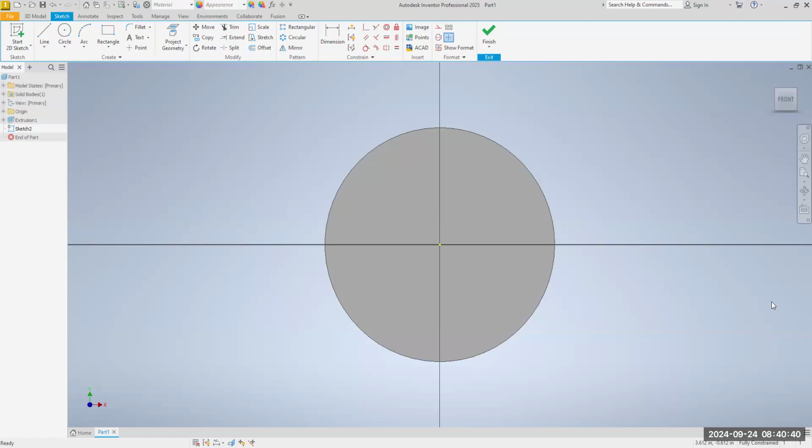Now, can somebody look at the drawing and tell me what the bolt hole circle dimension is? What is the diameter of the bolt hole circle? It's the dashed line. It's the center line. What is the diameter? Talk louder. It's 1.875 is what it should be. Okay? We're going to place 4 holes on the bolt hole circle and then 1 in the center.